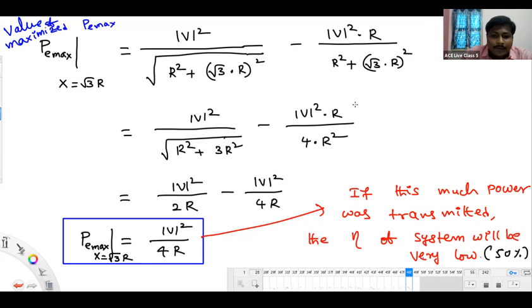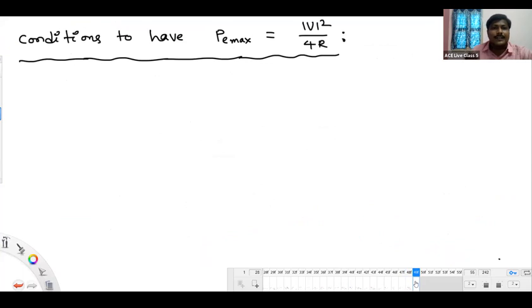So we can say maximum power transfer does not depend on reactance of line. No, that you should not say. Maximum power transfer value depends upon the impedance of the network, but you replaced the reactance value intentionally with resistance. That does not mean that it depends only on resistance here. Next, listen here.